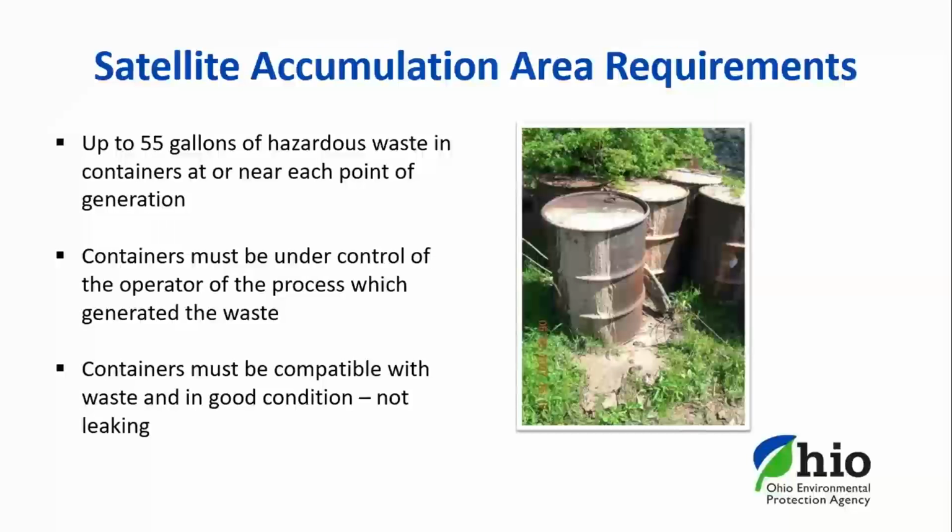The containers used to store the waste need to be compatible with the contents. For example, you wouldn't want to store sulfuric acid in an unlined steel drum that could cause it to corrode. And the containers need to be in good condition, so no dents, bulges, or leaks.